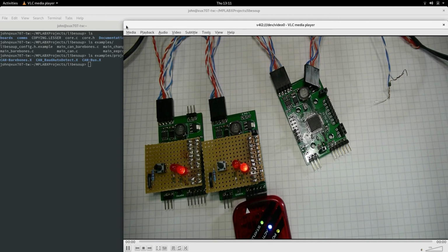That's it, because an API can hide all the details. There's more to it than this. There's retries. There's information requests. There's all sorts of stuff. But basically, you're sending an identifier with 8 bytes of data over a twisted pair differential signal, and I can show you that on a scope sometime. But it's very similar to RS485. And I'll leave it there.